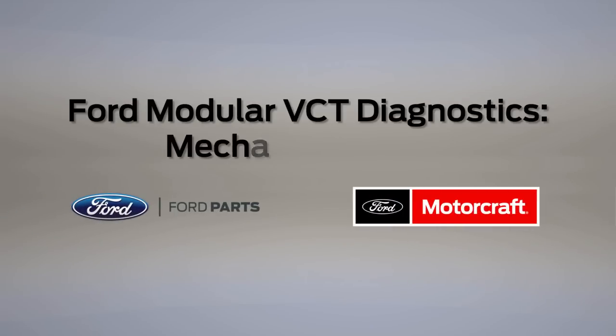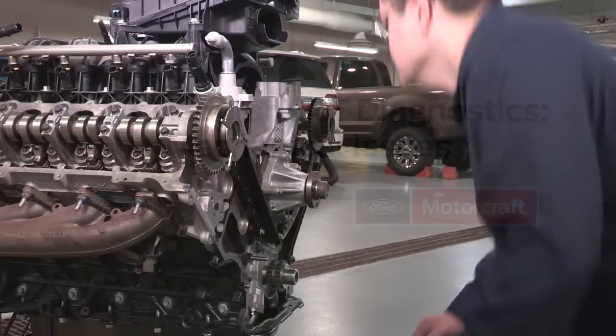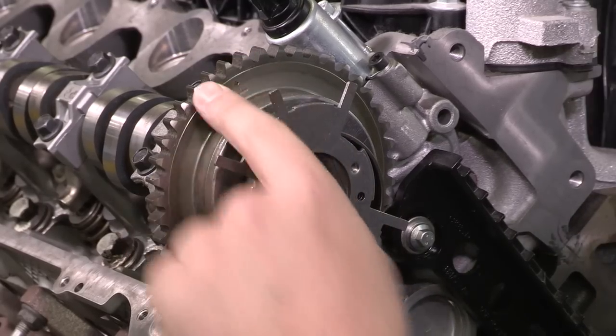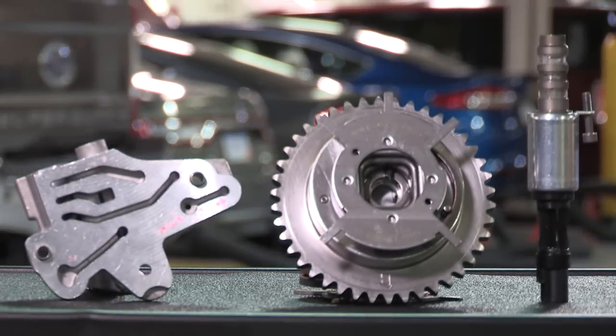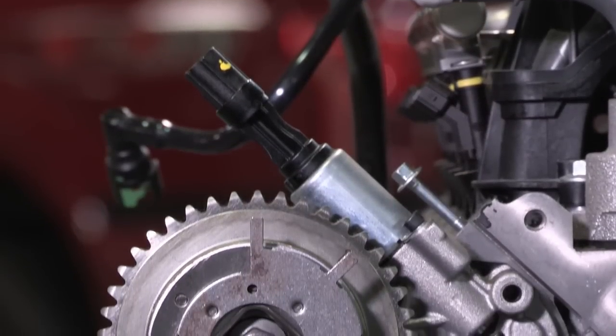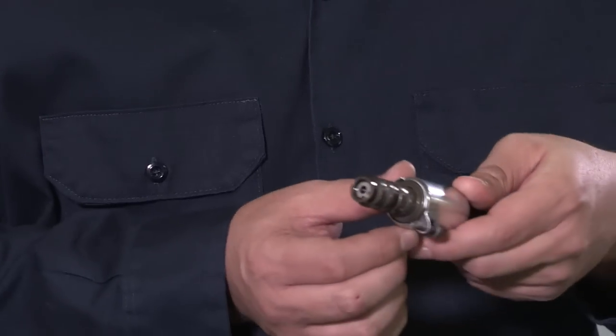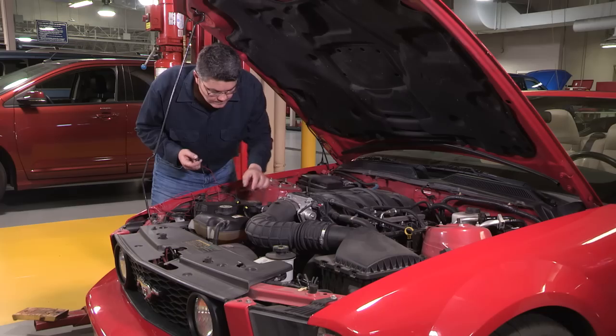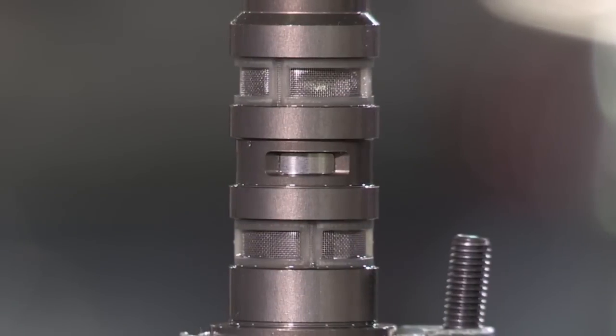When diagnosing a possible modular variable cam timing, or VCT, concern, mechanical failure can be a factor, so you need to check a couple of areas thoroughly. First, take a close look at the solenoid. When testing, make certain there are no physical or electrical issues affecting VCT solenoid functionality. Physical issues can be caused by lack of maintenance, and they can affect internal solenoid capability.